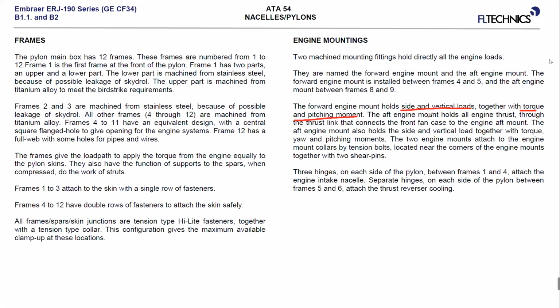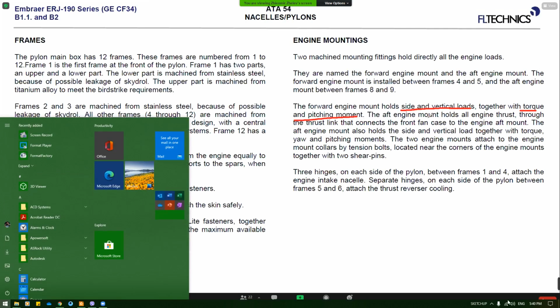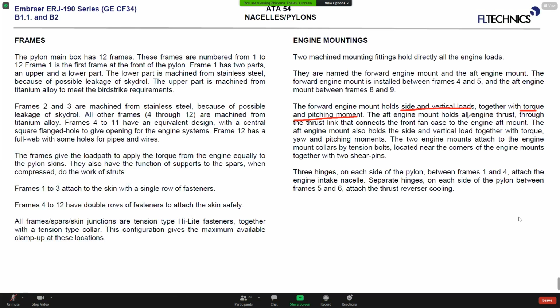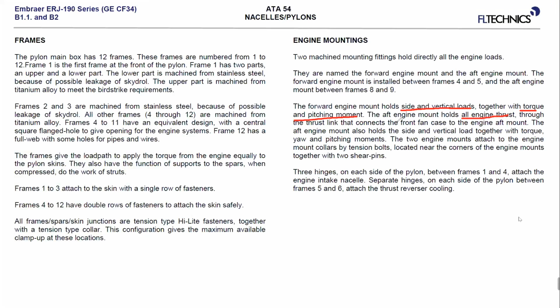The aft mount is holding also the engine thrust. All these mounts carry loads like the side, vertical, and torque. Just let me compare: side, vertical, torque, pitching moment.